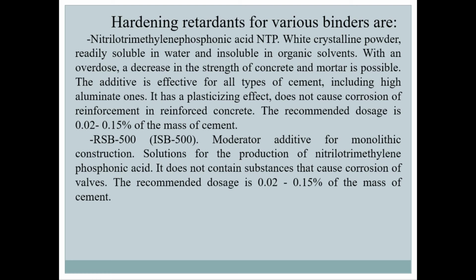RSB 500, a retarder additive for monolithic construction. Solution of nitrilotrimethylenephosphonic acid does not contain substances that cause corrosion of reinforcement. The recommended dosage is 0.02 to 0.15% of the mass of cement.